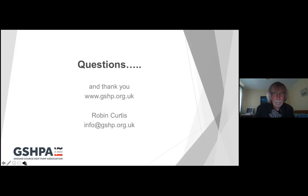Andy Howley's very helpfully posted how to Google for the MCS hydraulic design guide. And he's also commented the expansion vessel functions in reverse to steel pipe systems as the pipe expands faster than the fluid. So be aware of this too. You're absolutely right, Andy. You've got to know what you're doing when you're specifying expansion vessels, and it's true really on anything that's bigger than a domestic.